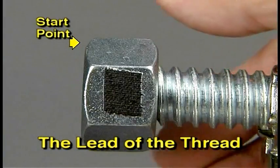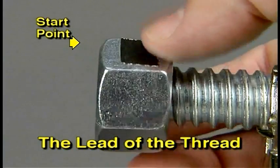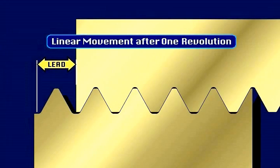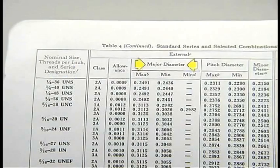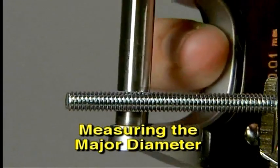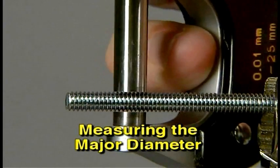The lead of a thread is the amount of linear movement that occurs during one complete rotation of 360 degrees of the mating part. The lead is normally not measured on a threaded workpiece. One important measure of a thread is the major diameter. It establishes the maximum material condition of an external thread. A thread any larger than this dimension would exceed the upper limit for the external thread.